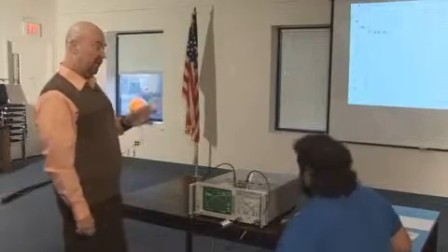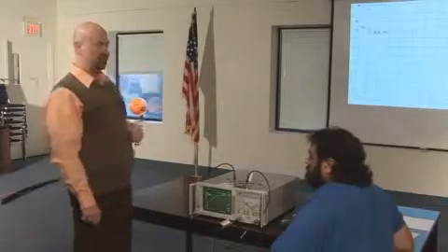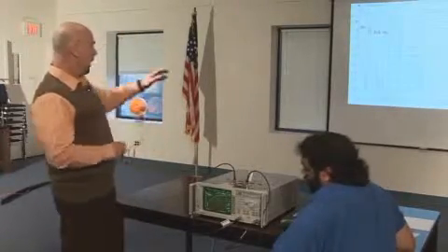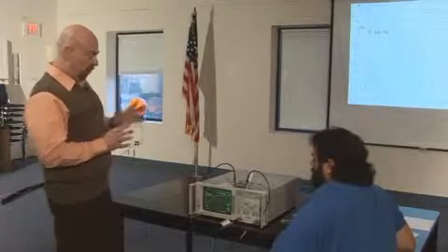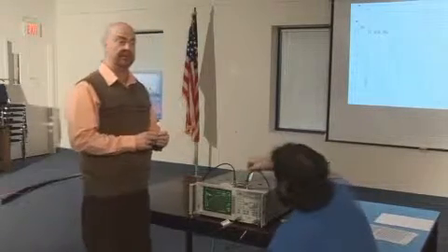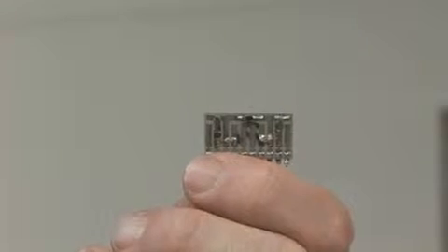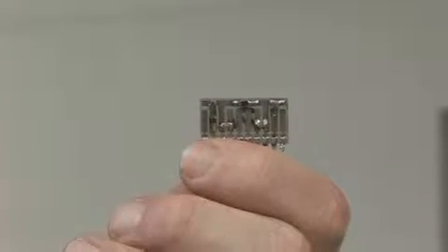So you still have to be right on with your final device. But this will give you a lot more rejection. Say that 30 dB before wasn't enough. You need 40. And you could also have rejection all the way along the slope if you need more. In addition, we have another type of filter which is called a pi filter. The reason it's called a pi is because it is shaped with capacitance in the form of the pi mathematical symbol.